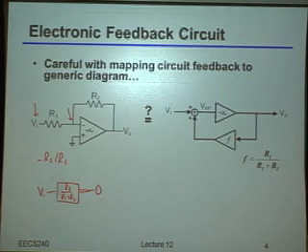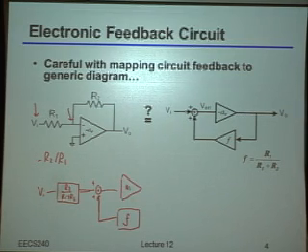So indeed, now if you do that, and then you apply the same block diagram that's shown on the right over there, which I'll just redraw here for the sake of clarity. Alright, so you have this system now. Then everything works out. Okay? And the reason that happens is that this attenuation just so happens to be R2 over R1 times F. And so because of that, when it goes through the feedback structure, you end up with the right overall closed loop gain.